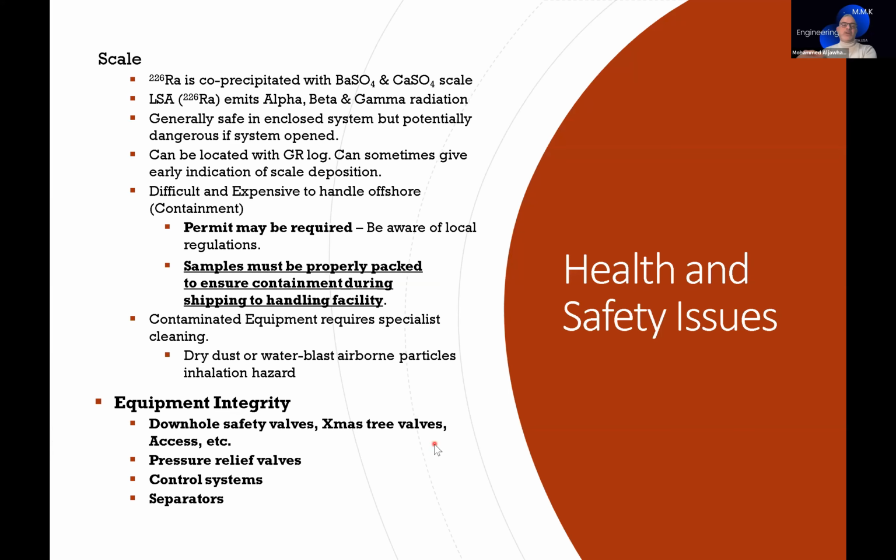Health and safety. We know scale may carry some radiation, so the scale deposition inside the wellbore needs to be handled very carefully. We need to study it well and do the lab water chemistry to know exactly if there is any kind of radiation inside, because it emits alpha, beta and gamma radiation, and it's generally unsafe for human beings.